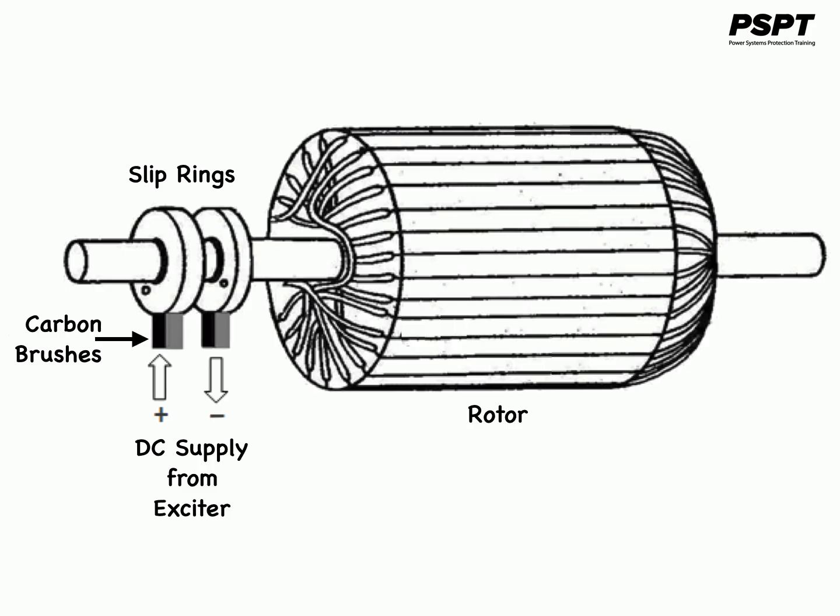In some cases, slip rings and carbon brushes are used to connect the DC supply to the rotating field. Slip rings are metal rings completely encircling the shaft of a machine but insulated from it. One end of the DC rotor winding is tied to each of the two slip rings on the shaft of the synchronous machine, and a stationary brush resides on each slip ring. A brush is a block of graphite-like carbon compound that conducts electricity freely but has very low friction so that it doesn't wear down or wear the slip ring out.